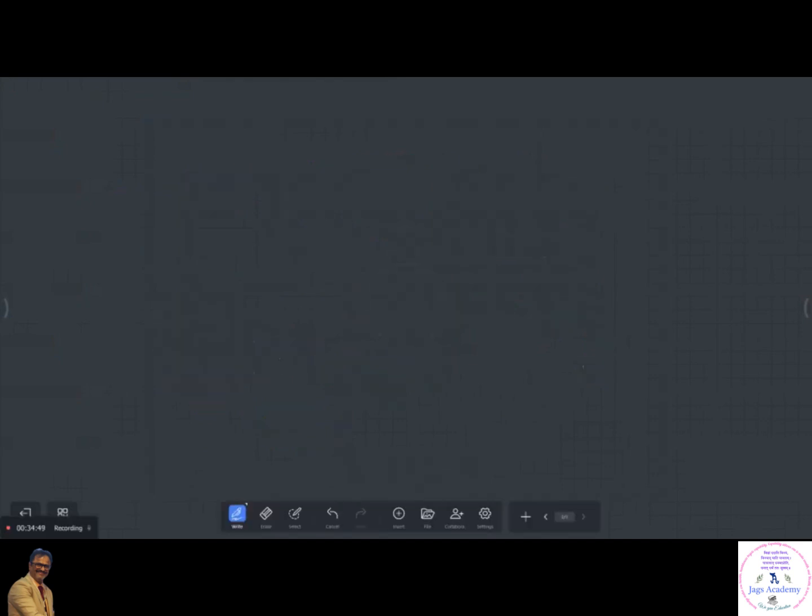Tell me, yeah. What data should I give first? MOV AL comma, what data should you give? What is the data? Suppose if you want to give 10000000, what is the data you should give? 80H, right? So MOV AL comma 80H. Now you do OUT 9CH comma AL. What will happen now? Okay, right?